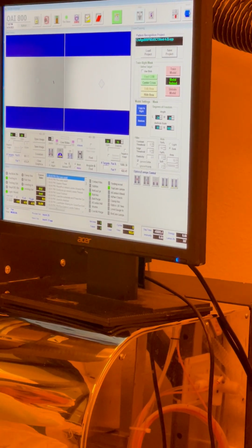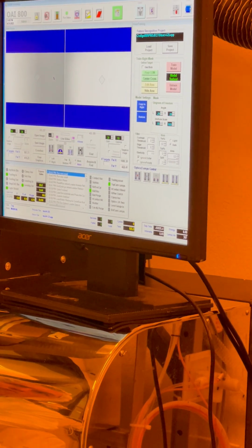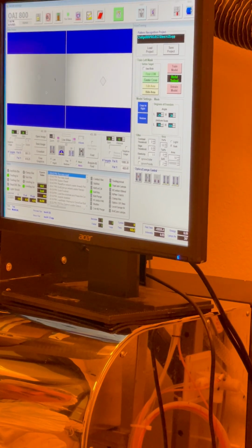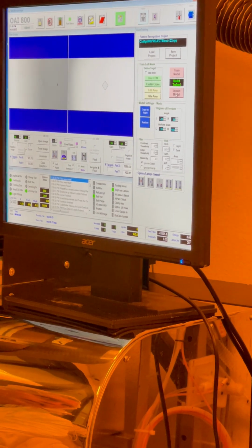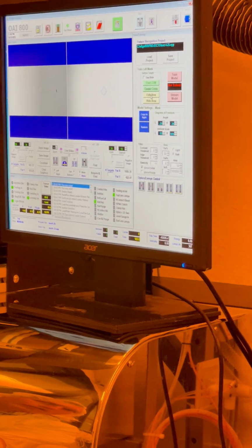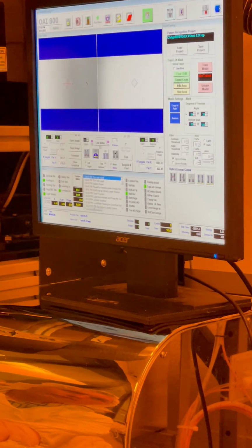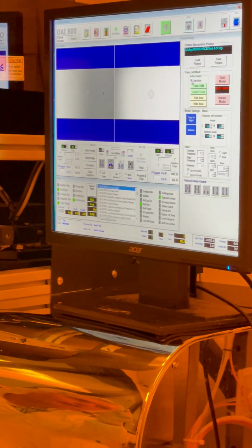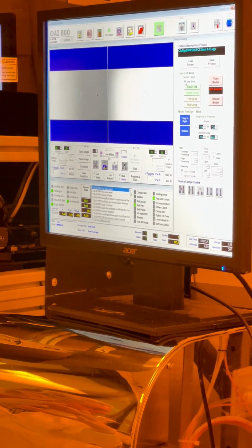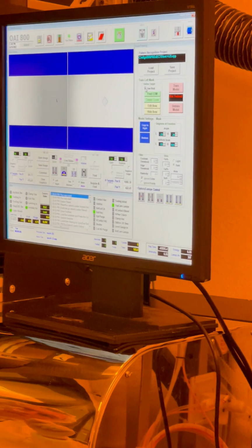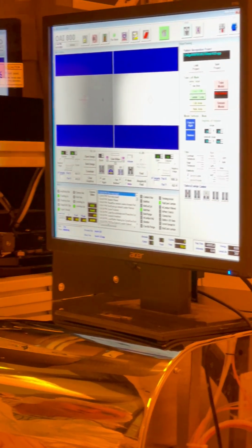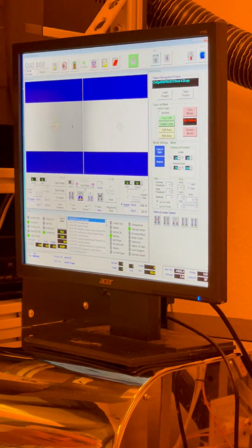Top is for the upper microscopes, bottom is for the lower microscopes. So if I wanted to train the left mask on the top microscope, I just select these buttons here, and I tell it to untrain the model, edit the area, and then I'm going to use blob. Blob means that whatever it finds, it's going to use the centroid of that area to find the center. If I don't use blob, then I manually drag across the center where I want it.